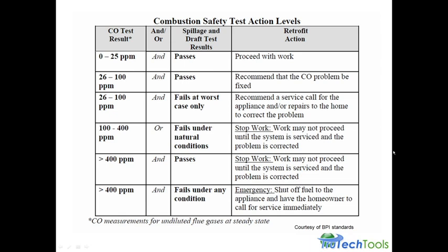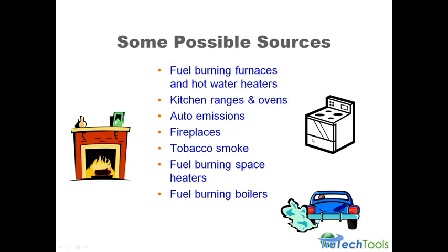There's sometimes problems where it produces large amounts of CO because of a lousy burner design. And there's just nothing you can do about that except recommend changing out the appliance. Most modern appliances you're going to be running well below 100 ppm, and they're typically somewhere around 20 to 30 ppm of CO maximum, and I see a lot of appliances running no CO at all.